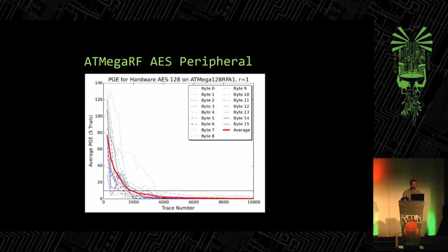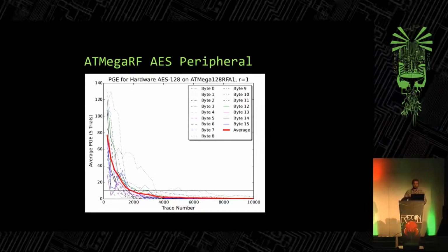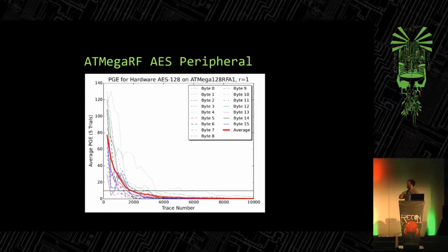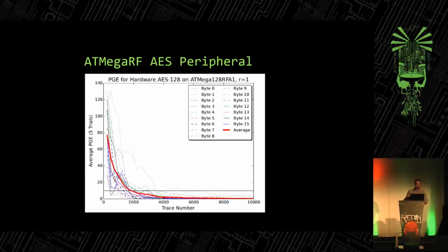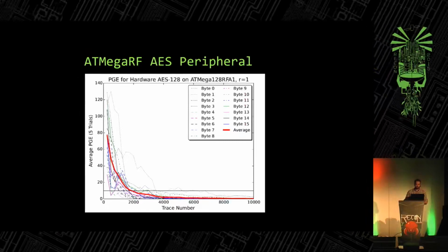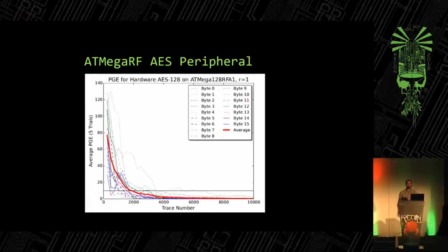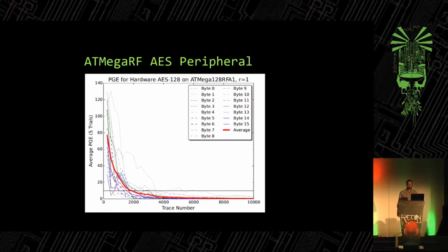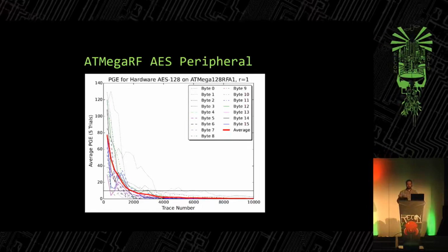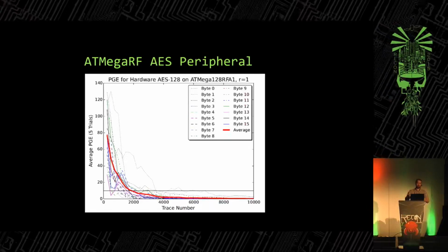So this is showing what's known as the guessing entropy. If the entropy goes to 0, we know the key with absolute certainty. So you can see the entropy is going down towards 0. Basically, if you can send the device 10 to 20,000 messages, you can recover the key. And for the 15.4 node, that doesn't take very long.